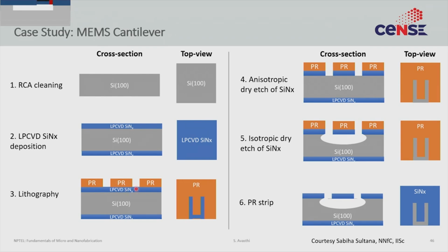The exposed silicon nitride can now be etched. So after this, you would do a dry etch. So this would be in plasma. I think the dry etch is being covered in the next module or in the module before this. I don't exactly remember, but you will get to a dry etch at some point. Just take my word for it that we'll do the dry etch.